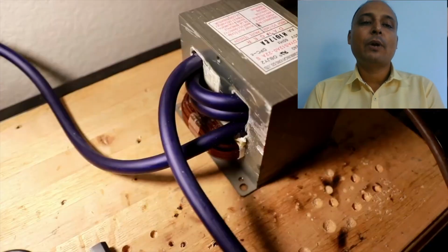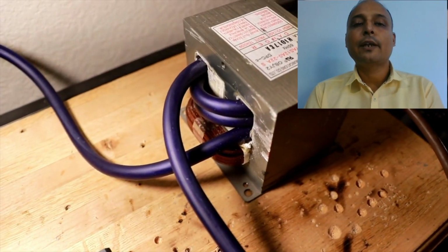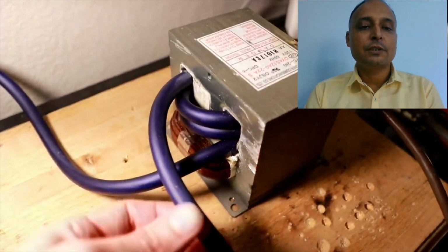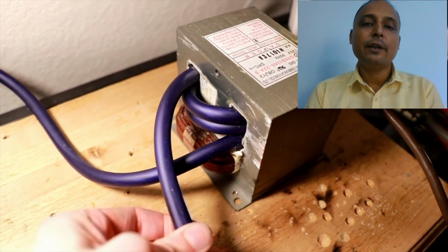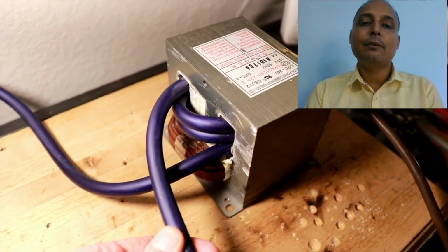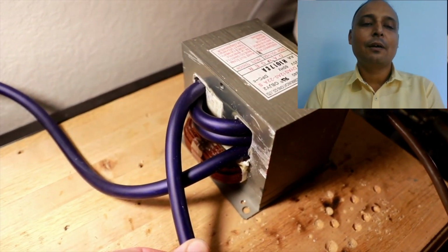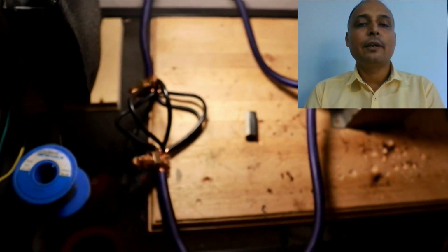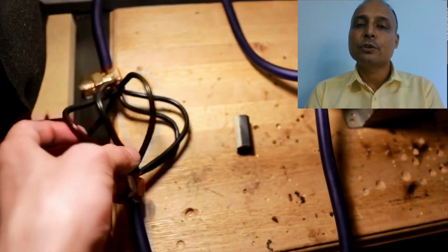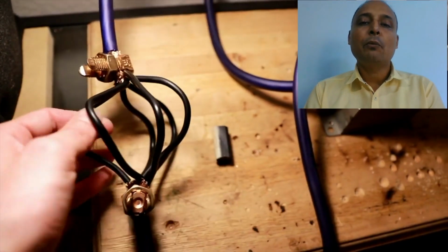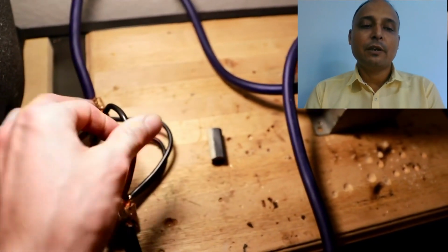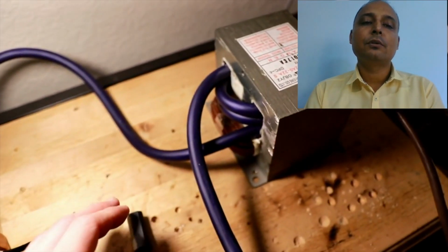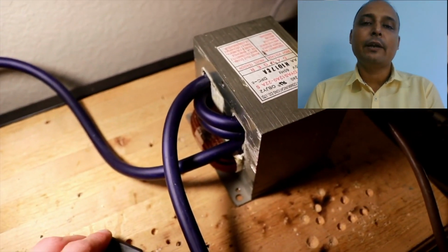So this particular wire can become very hot at times, so we need to be careful while doing such a kind of testing by short circuiting. It should not be supplied for a long time while doing the testing. When it is connected to the load, then the amount of current that flows through the secondary becomes low. But when it is connected in this manner, in a short circuited manner, then the amount of current flowing through the secondary wiring is very high.